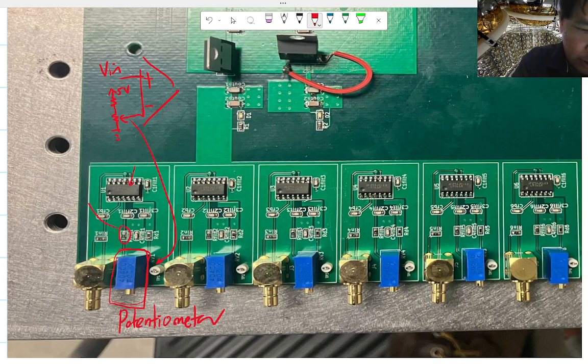There's an additional resistor here. In fact, I think it's the one on the right. Sorry about that. It's up here. And then you can change this potentiometer so that it has a very fine voltage. We set these at about 5 millivolts. The reason we do this is that this is designed to detect signal from a photomultiplier, meaning it's just a signal from light.